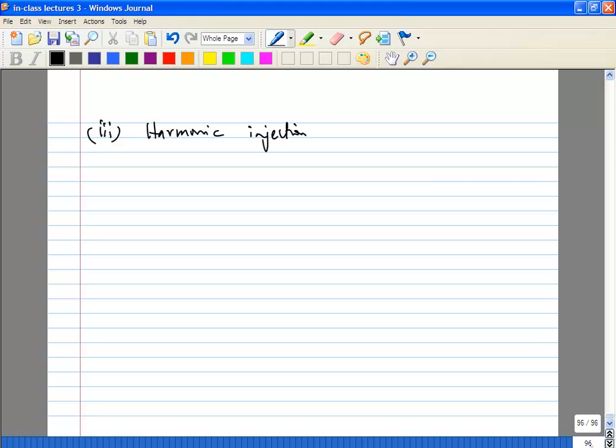Harmonic injection. What you are relying upon, remember, is that the output voltage of the oscillator is purely sinusoidal. Especially the differential voltage is going to have the component which you need, plus maybe the third, fifth and so on. But each side of the oscillator as well as the common mode nodes are all going to have the even harmonics, because the oscillator still has some operation in the even harmonics, even though it's undesired.